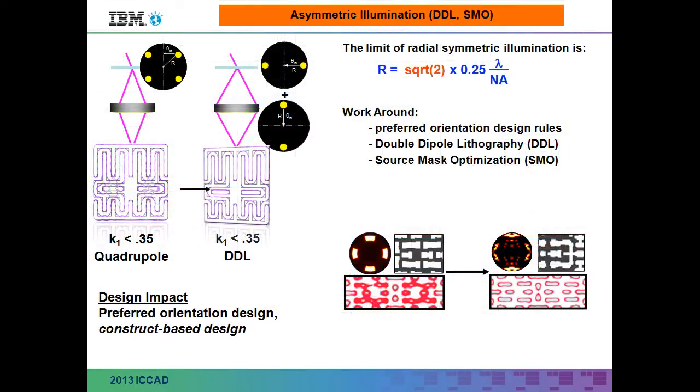And that something new has to do with sort of simple geometric constraints, right? I told you that the resolution limit of normal lithography is K1 of 0.5, then you tilt things on the side, now you can get a K1 of 0.25. Well, that was a bit of an oversimplification, right?